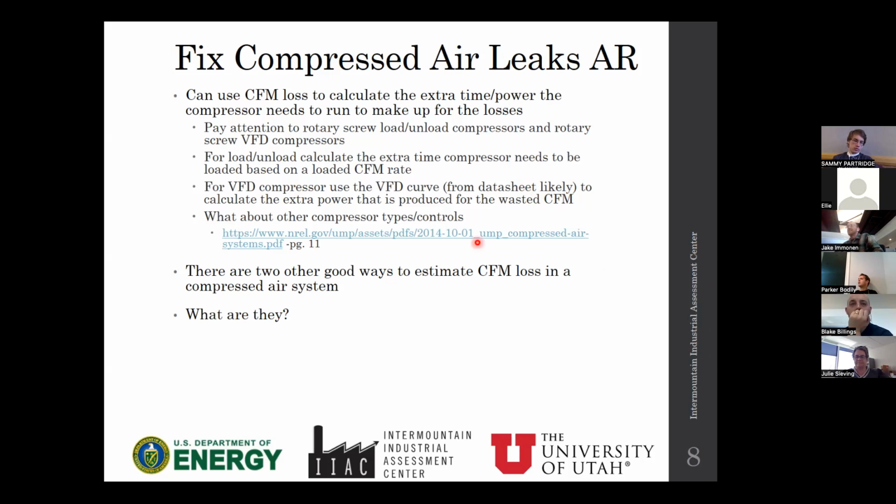Go for it, Sammy. You can record, I mean, if they turn off the air compressors, you can record how long it takes for the system pressure to drop down. Or how quickly it drops. That's a good one. Yeah, that's on my list.